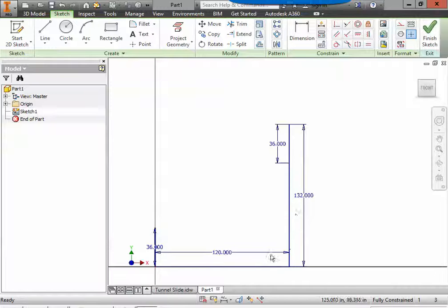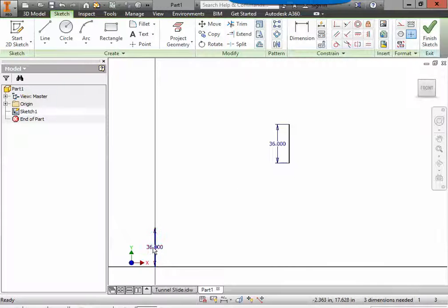These two lines that we drew for layout lines can now be deleted. So we're going to drop all our tools with Escape, click on the line and click Delete. Click on the line and click Delete. And we're left with our two lines. I'm actually, while I'm at it, going to move my dimension a little out of the way. And I'll move this one outside.